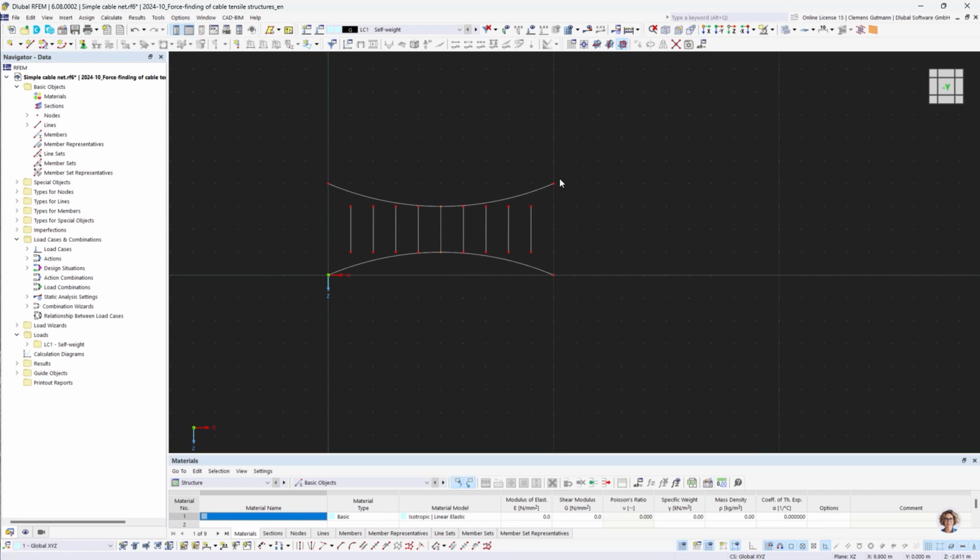And I want to connect those straight lines now to the arches, and there's a quite handy way to do this. There's an option that has not been too long available in the software, and that is the extend graphically command. There's the opposite command as well, the trim graphically. It does the same, but the other way around.